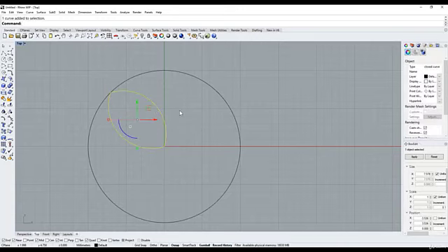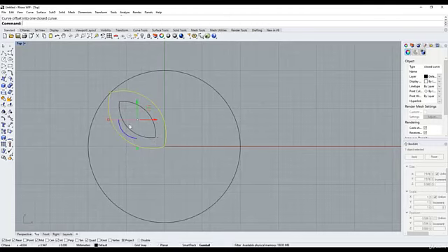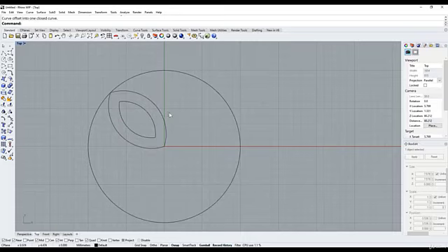And I'm going to offset this. I'll just type offset, and I want to offset that on the middle. And you can see the distance we're offsetting is 1.8, and if I change that to say 1.4, it gives us a little bit of a finer edge there.